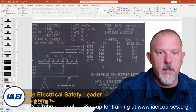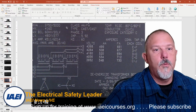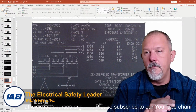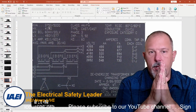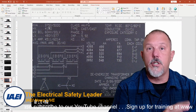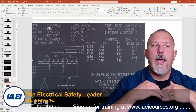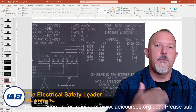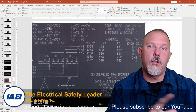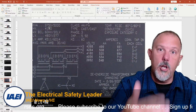So this was the nameplate that we were looking at, and if you'll notice, I have AA/FA, which has 2 different kVA ratings. It's because I'm adding fans. So you are putting fans on the transformer to control what happens with the heat, right? I'm able to push more kVA through this transformer because I am cooling it with these external methods, so I can handle more load.